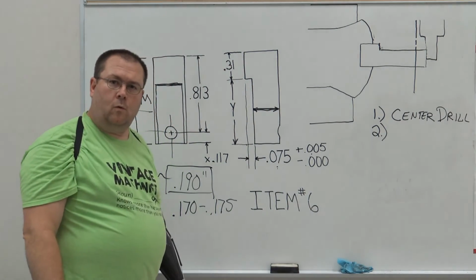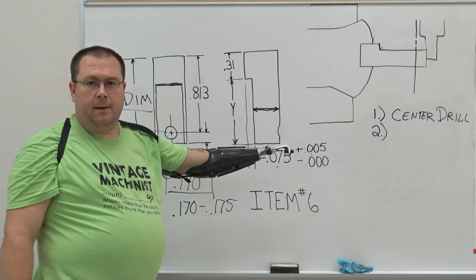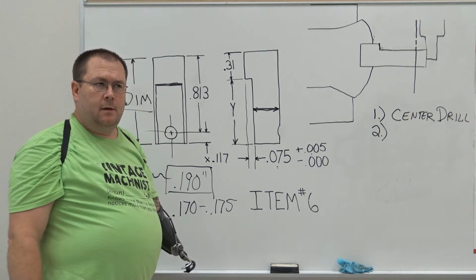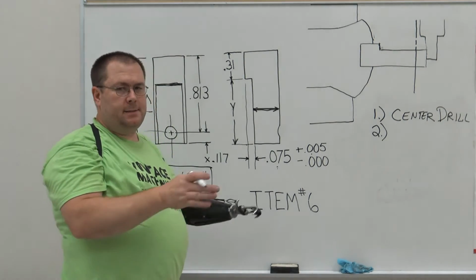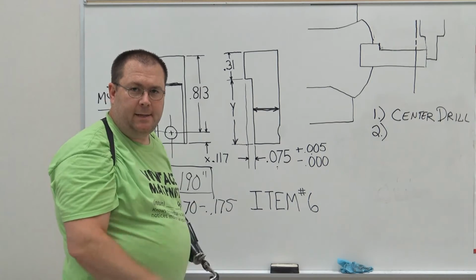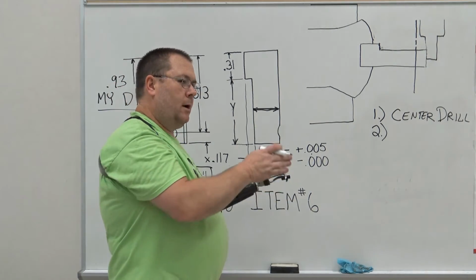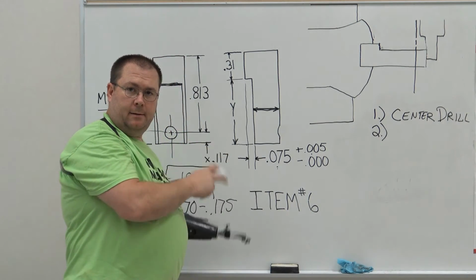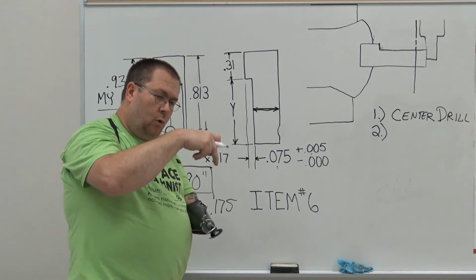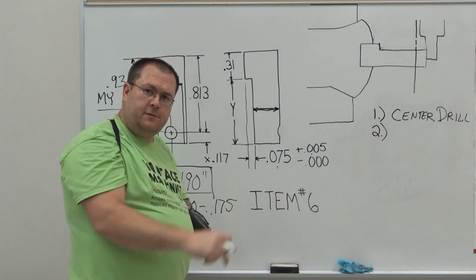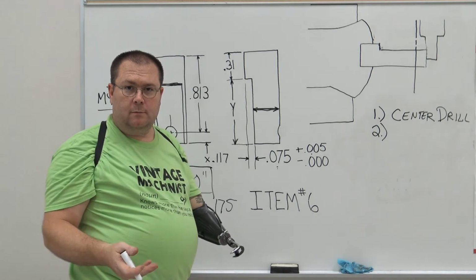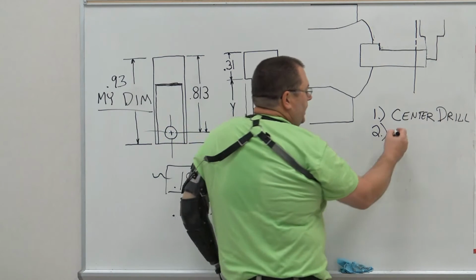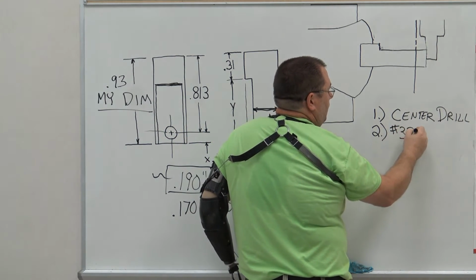Next step. We want to drill the hole. Well, we want to ream it ultimately. We've already decided that because the precision of the hole requires it. So if I take 126 minus the magic numbers, right, 8 to 10 thousandths, I want to be somewhere in the 116 to 118. Well, if you recall back to doing the hole in the top of our crankshaft, that offset hole, we used a drill that measured just that, 116 thousandths. And that is a number 32 drill.